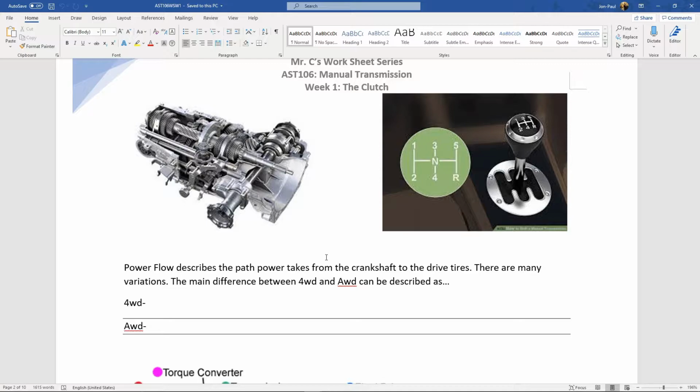And then if the engine is mounted transversely, and I'm going to show you when we get to drivelines in week 3, but like an Evo does this, a bunch of the Nissan, I think most of the Subarus now, the engine is mounted transversely with a transaxle right there in the driver's side of the front, and then it just has a third drive shaft coming out of the transmission to go to the back. So that's one definition.